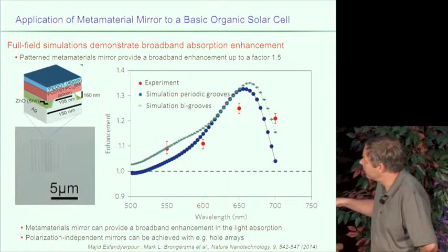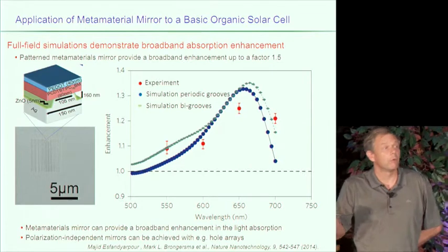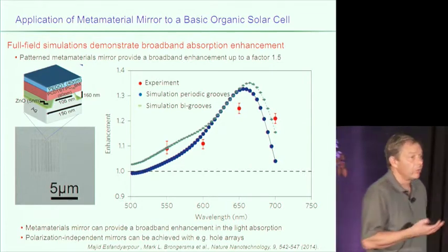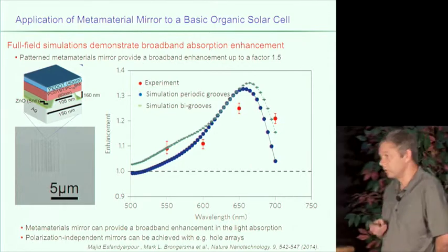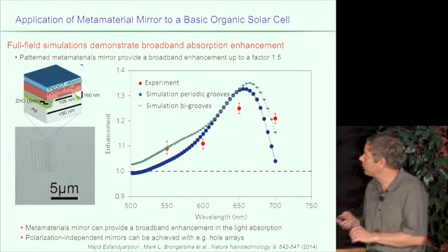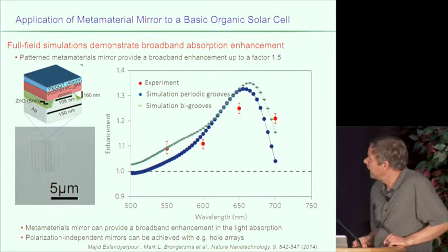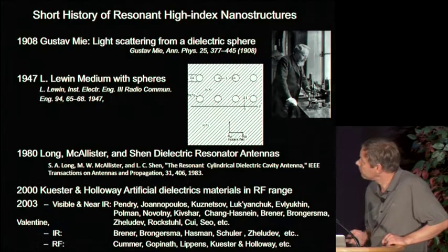And we can see here a broad enhancement of a few tens of percent over a broad range of wavelength in the photocurrent in the region where we made the grooves inside the metal. So the simple step of making grooves can significantly enhance efficiency.